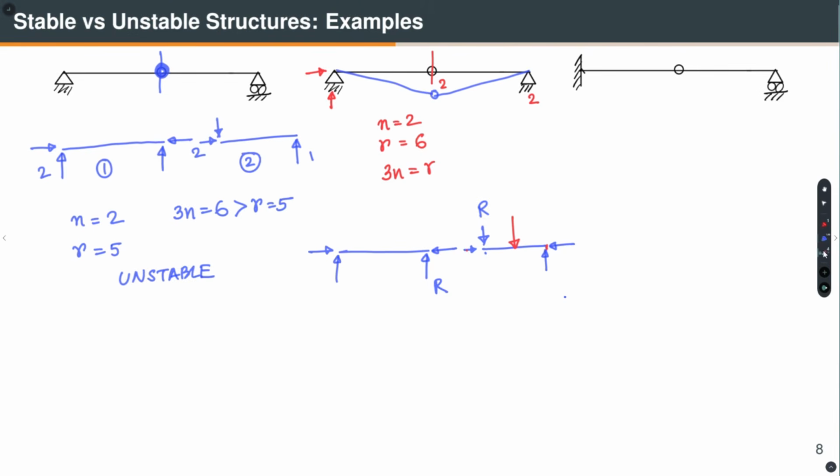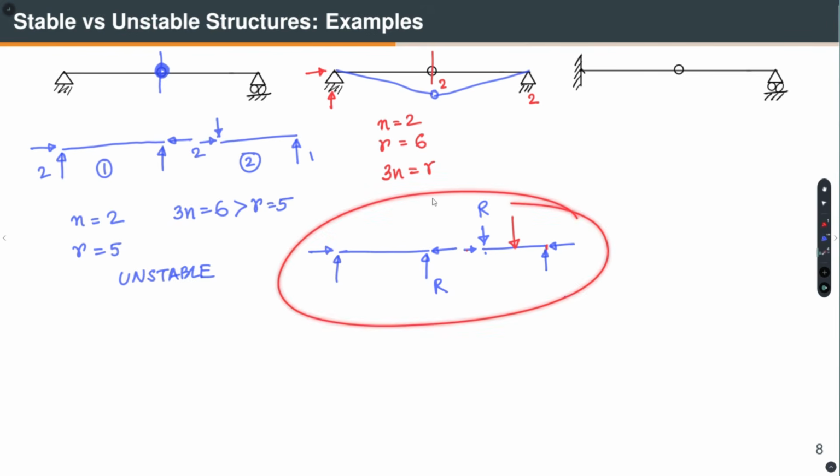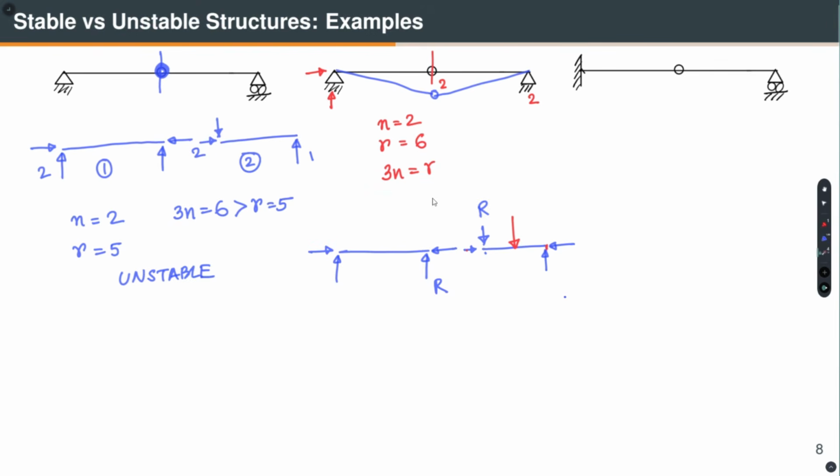This is what I have done. I have considered the equilibrium in the undeformed configuration. But when we actually get into nonlinear analysis, you will see that I can write down the equilibrium equations for this case in the deformed configuration, and then as we can see, from reality also, if I apply a little bit of load, it displaces, and then as I keep increasing the load, it can take load. But that you can do only if you perform a nonlinear structural analysis.